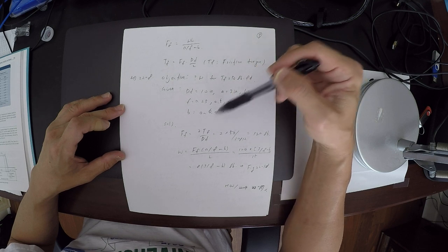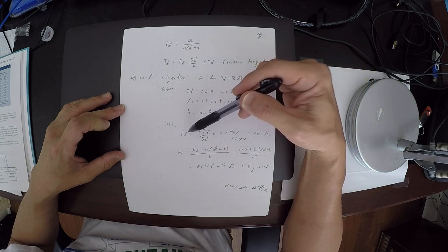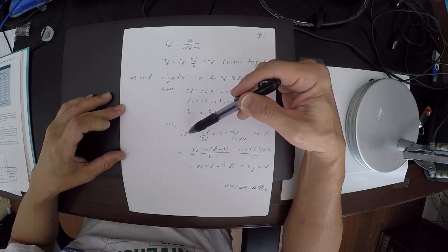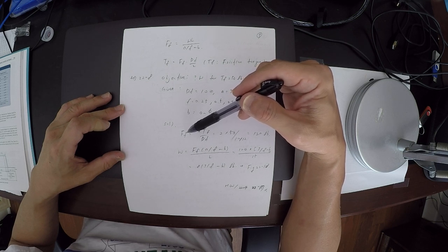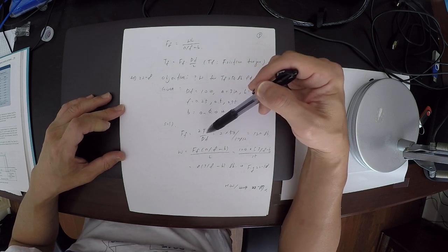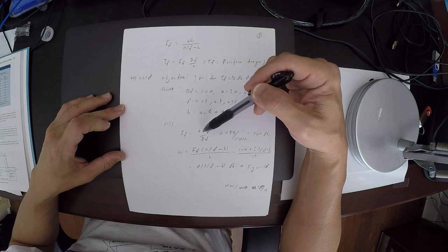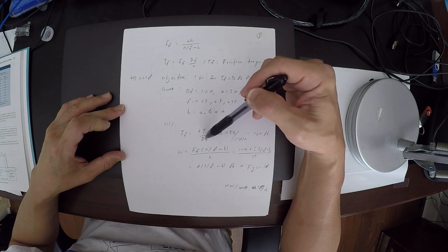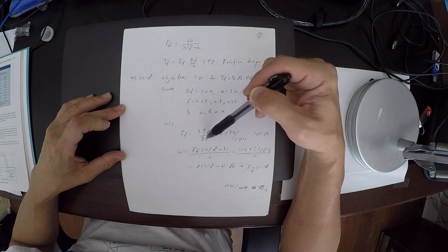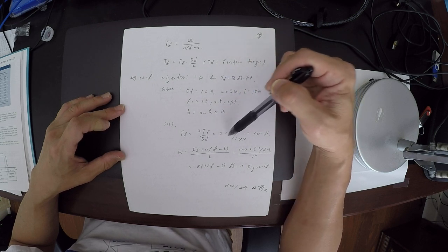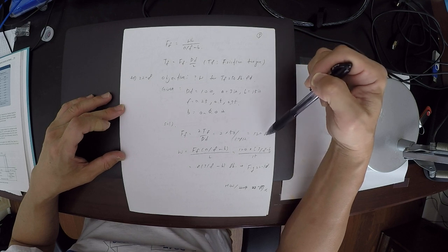You can calculate Ff, which is the friction force that's going to occur at the contact point between the drum and then the friction pad, which will be simply Tf over R, because the diameter is given. You need to just divide it by 2. So that gives us 120 pound.